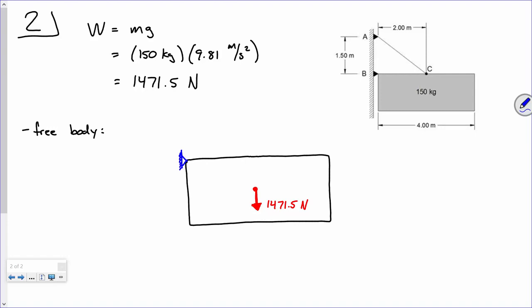Now, I have a hinge at, we're calling it B, right? Or a pin at B. What must be true about what's going on at B? Anytime you see a pin or a hinge, what does that tell you? The sum of what must be 0 there? Sum of moments, right? See, I can take this door and I can freely rotate about the hinge. I can't take the door and yank on it, but I can rotate easily. See what I mean? Same thing here, okay? So, the same thing is true at A or B.